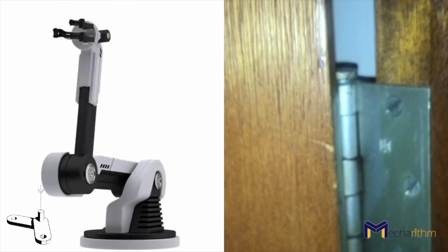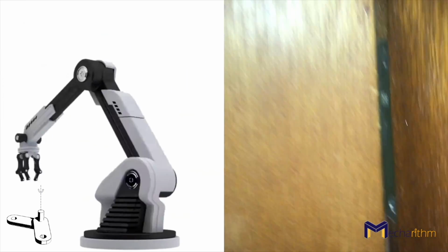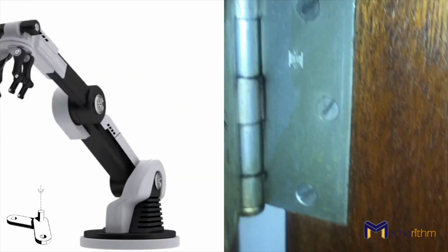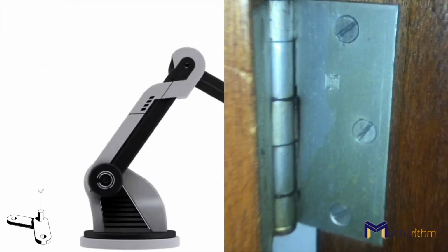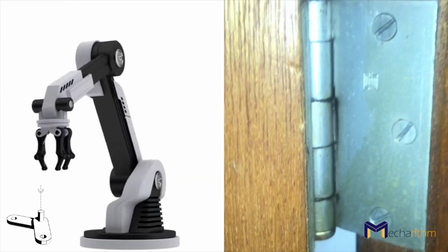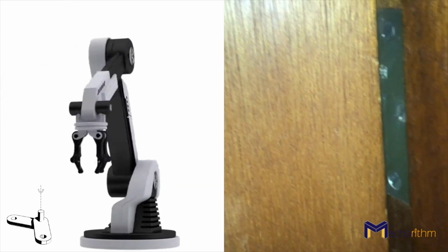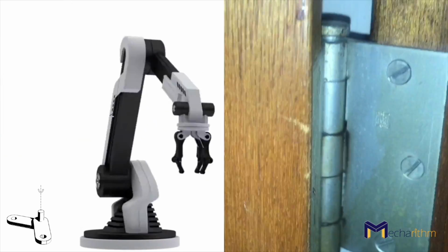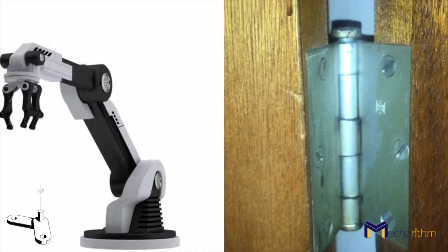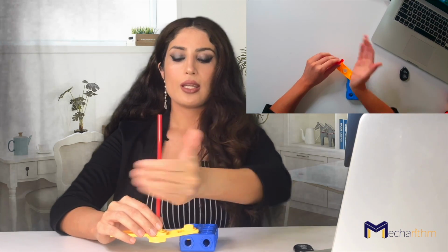So now let's see how many different joints are used in different kinds of robots. A Revolute joint, as we saw in the industrial robot of the previous video, is like a door hinge. It provides 1 degree of freedom of motion between the 2 bodies that it connects. The rotation is around the joint axis, and the positive rotation can be determined using the right-hand rule. According to the right-hand rule, if your thumb is in the direction of the rotation axis, the positive rotation is the direction where your fingers curl.